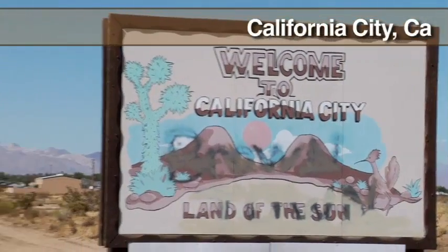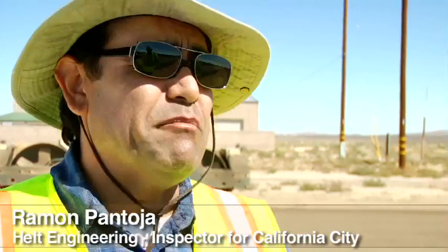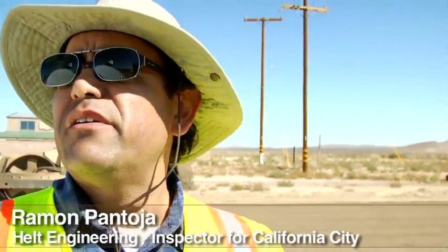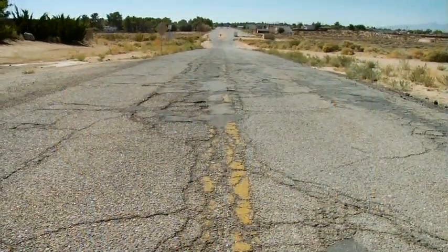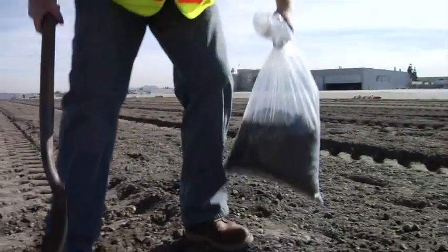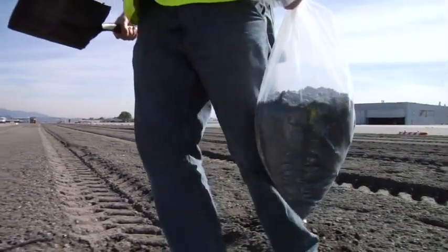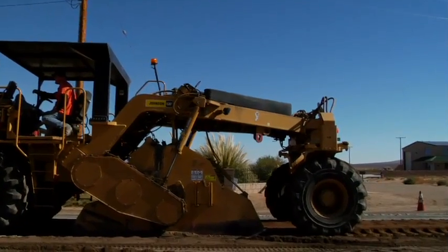This particular location was chosen because this is a perfect example of subgrade failure, which in this case, if we go with conventional construction, will be very expensive. Basically, over the years, the city, the agency, paved over desert mix. The soils engineers took samples of the existing pavement conditions, and then therefore, they decided to recommend the FDR process. Now, with this process, our intention is to have a very strong foundation for this job.